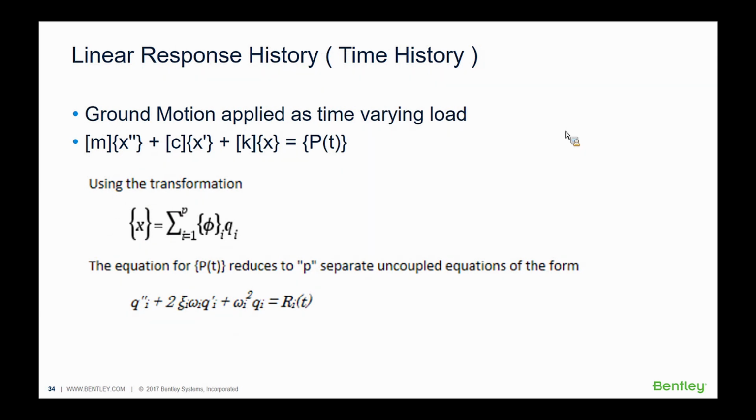Now moving over to the other form of dynamic analysis, which is response history, also referred to as time history. In this type of analysis, the dynamic force is applied as a time versus force data. This type of analysis is most widely used for analyzing structures under dynamic loads from vibrating machinery. I've also seen this type of analysis being used for blast analysis.